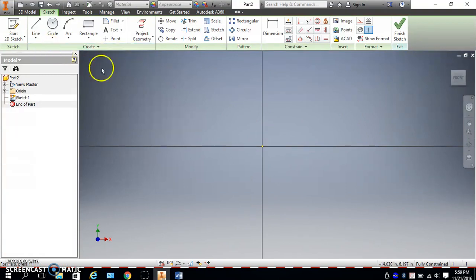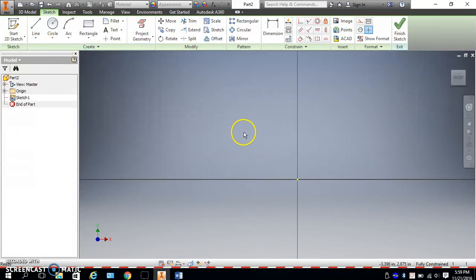So what we're going to do now is we're going to create a simple square or a simple rectangle with lines. So you're going to hit line. We're going to hover over, and you notice that this yellow dot pops up. Right, that's what happens. I'm in a command right now. You notice also there's the XY coordinates that tell me where I am on the screen. Now I'm going to hover over the origin, and notice that that dot snaps to the origin and it turned green. Right, so it tells us now that you're snapped to, that you're connected to that origin.